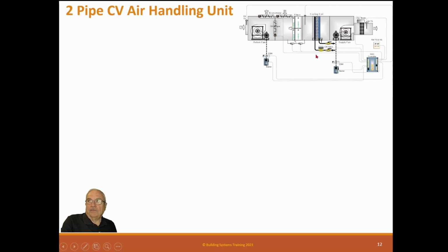space. Now, if you're in an economizer, then this damper closes, this one opens, this relief damper opens, the outside air opens, and what happens is the outside air comes in and cools the space. Return fan takes it and pushes it out of the space. So this is how an economizer works, and why we have it.